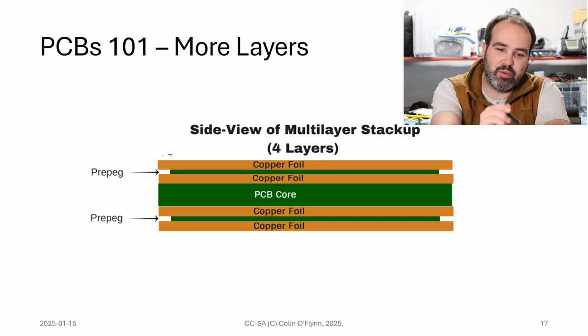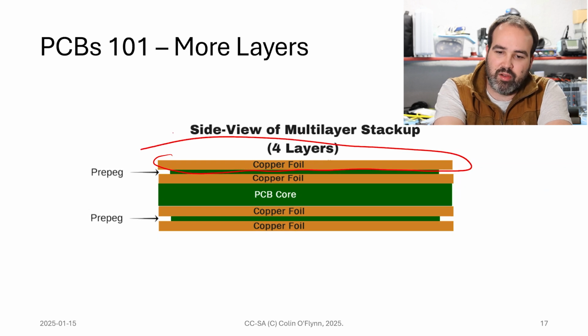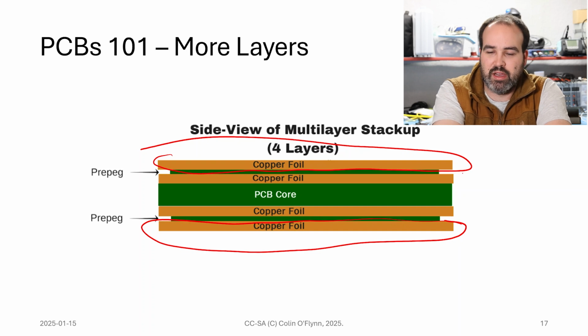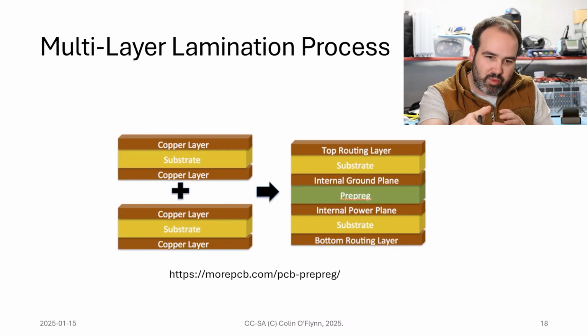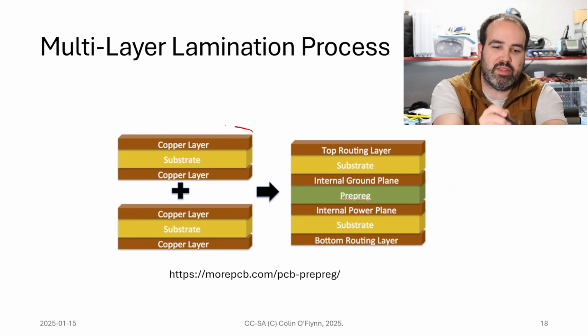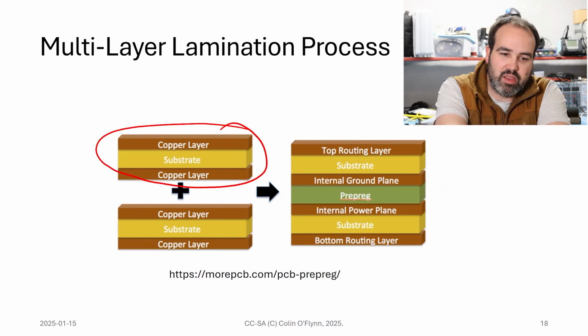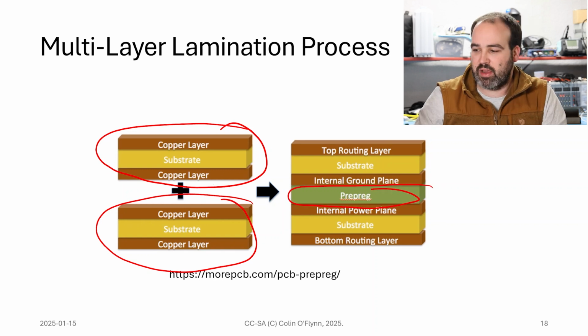With our PCB, that was the top and bottom layer, right, when we talked about this. We can have more internal layers, and internal layers are inside. How this is made actually varies. So this is one way of making it. More commonly, we have this system where you can see it's basically like two two-layer boards that get stuck together with a pre-preg, this in-between board.